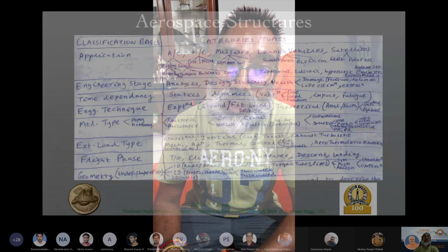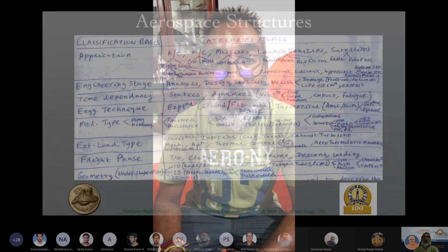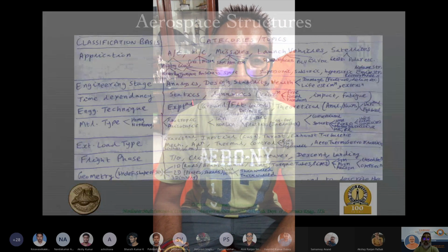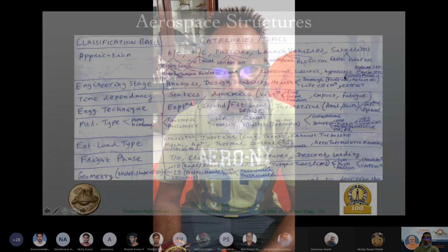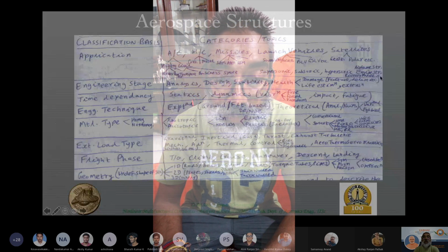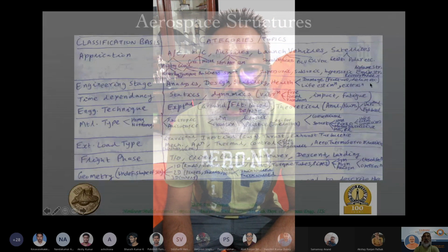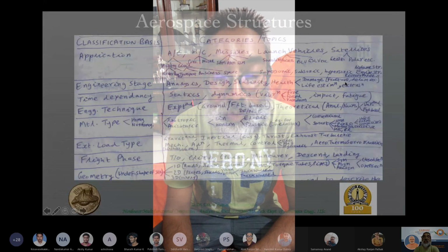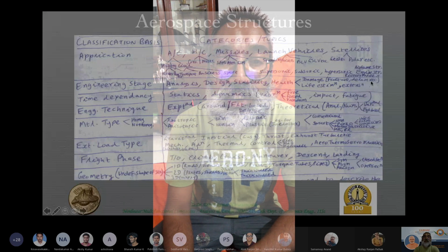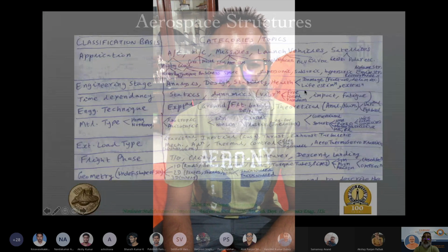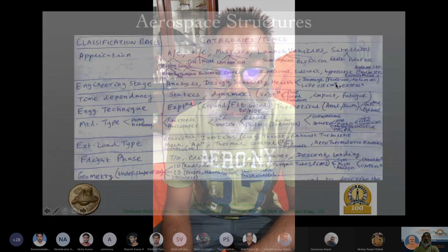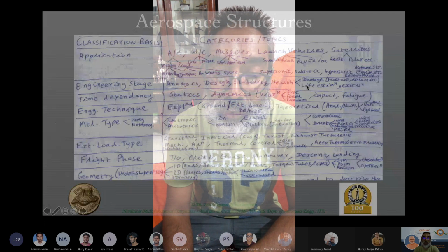But if you're looking at the health of the structure, we have what is known as structural health monitoring, or SHM, and there you try to understand the damage mechanics, both in terms of the fracture mechanics, which we will touch upon, and also, in the case of composites, the delaminations, fiber matrix debonding, fiber breakage, matrix cracking, etc. And those will then help us to understand how we can estimate the life.